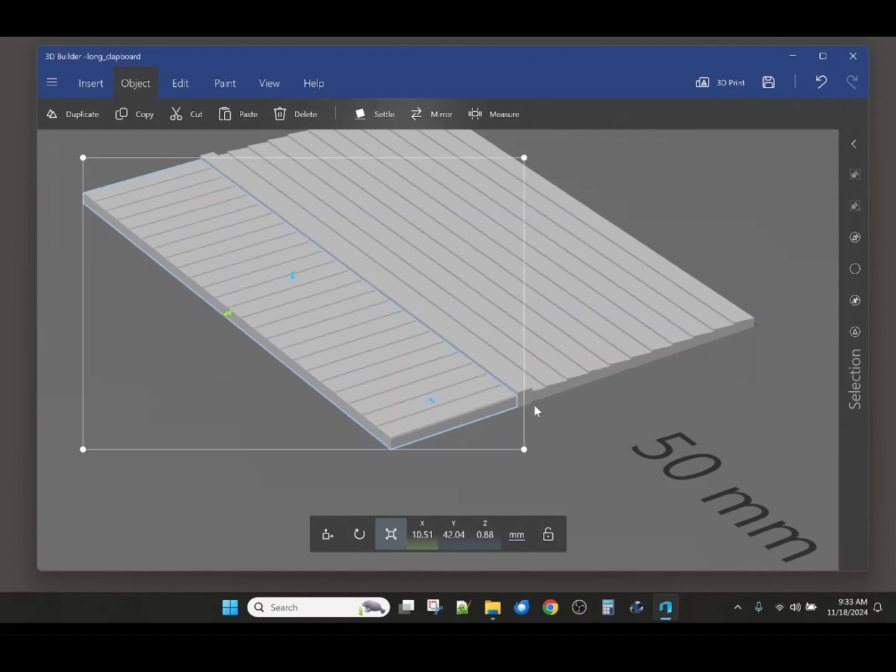And the 4-inch thickness allows the trim to lie on the floor of the X and Y axis along with the wall parts. If you give any of these parts an unintended Z or vertical axis movement, you can easily correct that using the Object Settle tool in the menu ribbon, which will lower the selected part to sit on the XY floor.